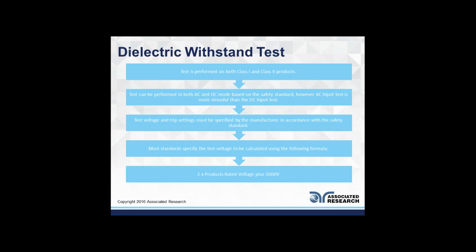Class 2 products would be tested with the return path being an external representation of a palm, maybe aluminum foil wrapped around some foam placed over the product to detect the leakage current. If the insulation were to break down through the plastic, it would create a breakdown condition on your aluminum representation of a hand.